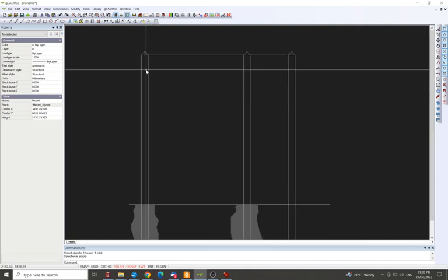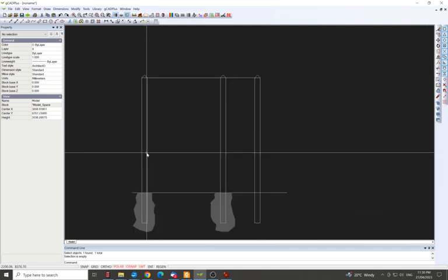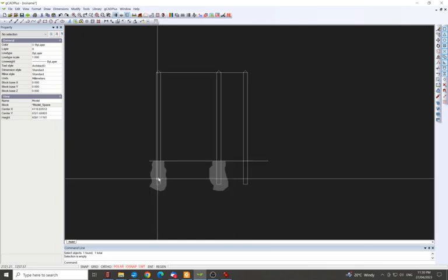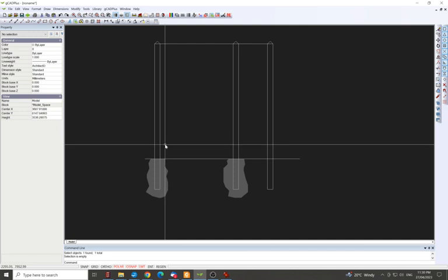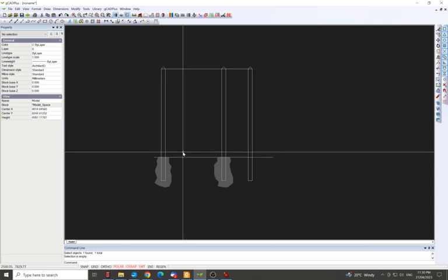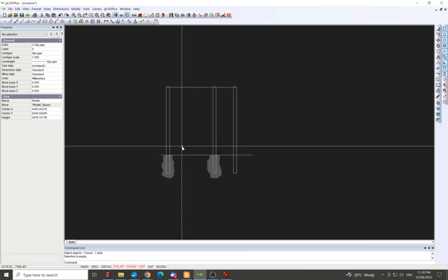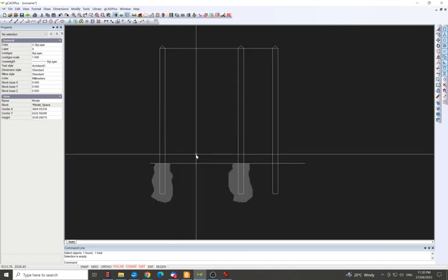Generally, the general rule is you put the hinges on the back of the post, so you don't put them on the side in here, you put them on the back right here, especially for outside gates. It allows them to be easily adjusted, because things move in the ground, they're not on a house slab, so this could move a little bit. Plus they're heavier than doors, so usually big brackets, so you want a bit of room and strength to mount them, and they're always stronger on the back sitting flat than on a 90-degree angle. So it's important to get these all quite plumb.